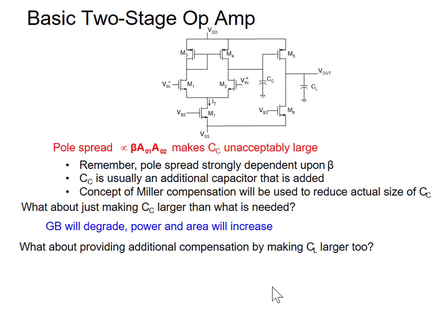You will decrease your phase margin. If you put very much on there, you will maybe even oscillate. Okay. So more is not better. Poles will move together and degrade performance.